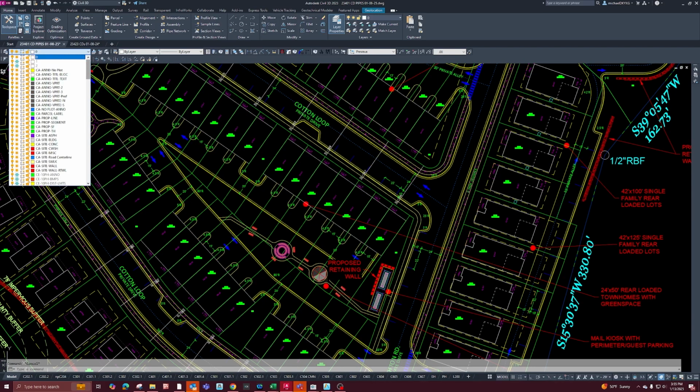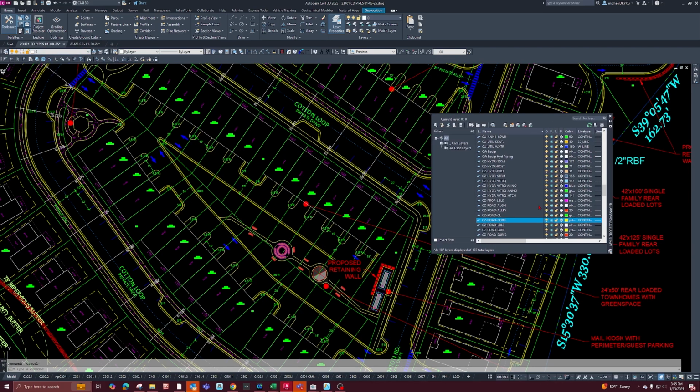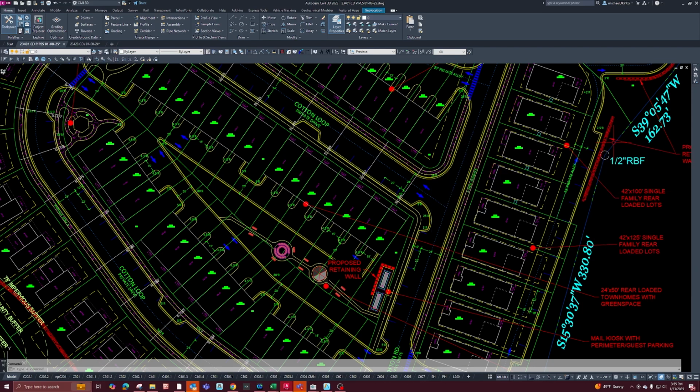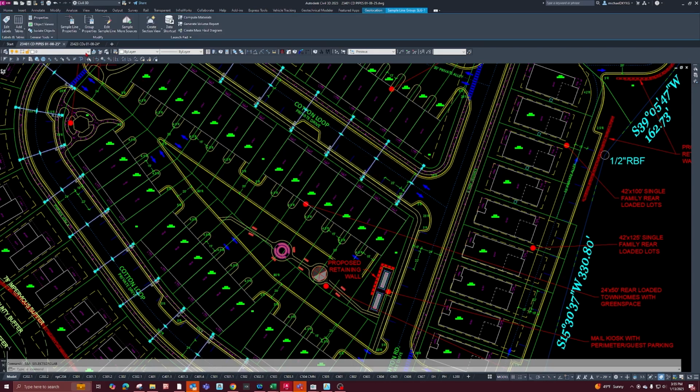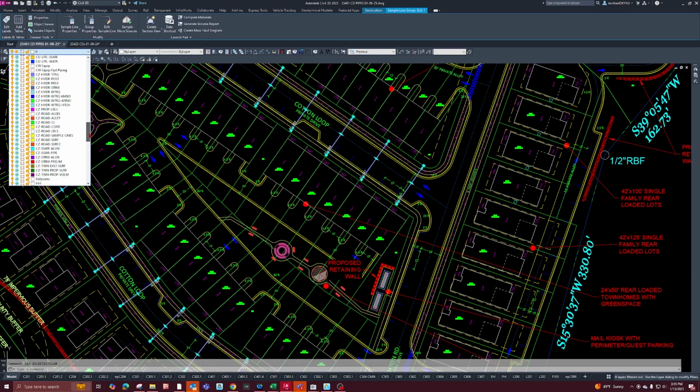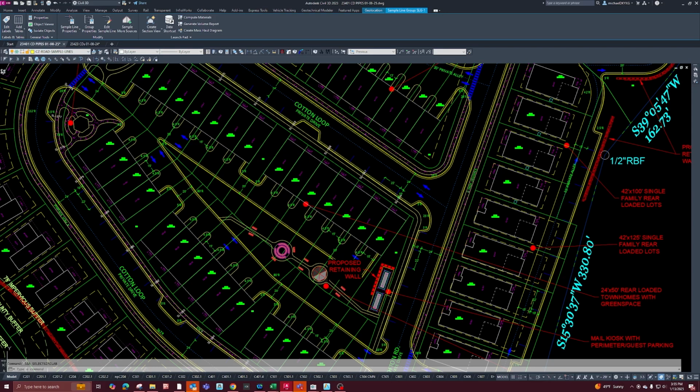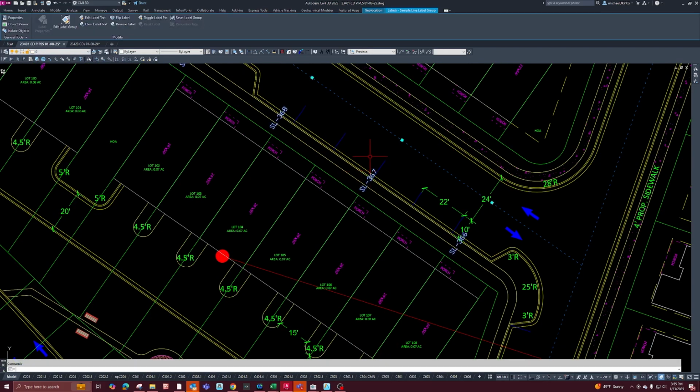So we're going to want to make a layer for these sample lines. Call it CZ Road Sample Lines. You can select one of them, SSA, go to the drop down, and then put it on that sample line layer as well as the labels for it.